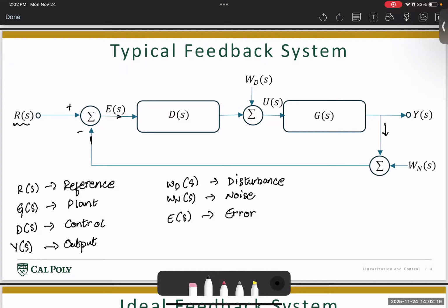Then at that point, our Y of S is 5 degrees, our R of S is 5 degrees. Then our total error signal, which is basically the difference R of S minus Y of S, cancels out once the output of the system reaches 5 degrees, and we provide a zero input to the control, or in other words, the aircraft just holds its current state.